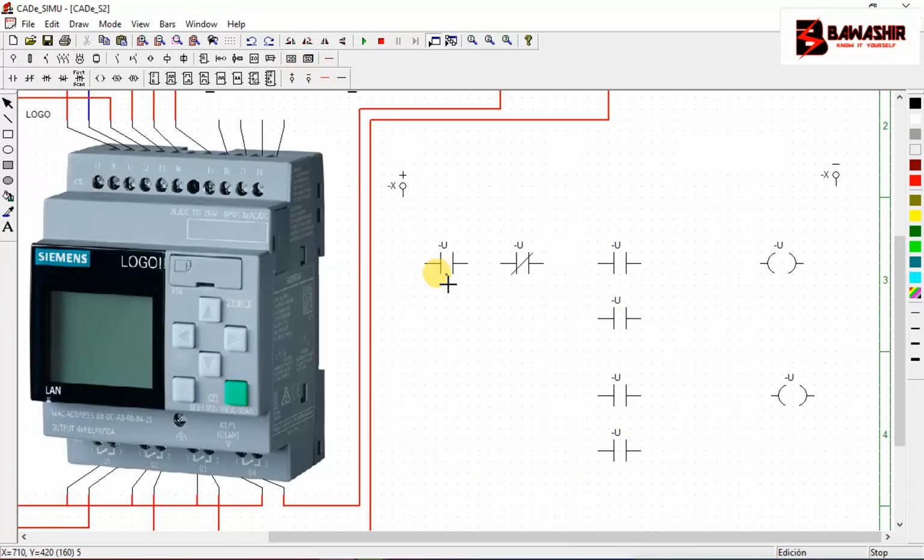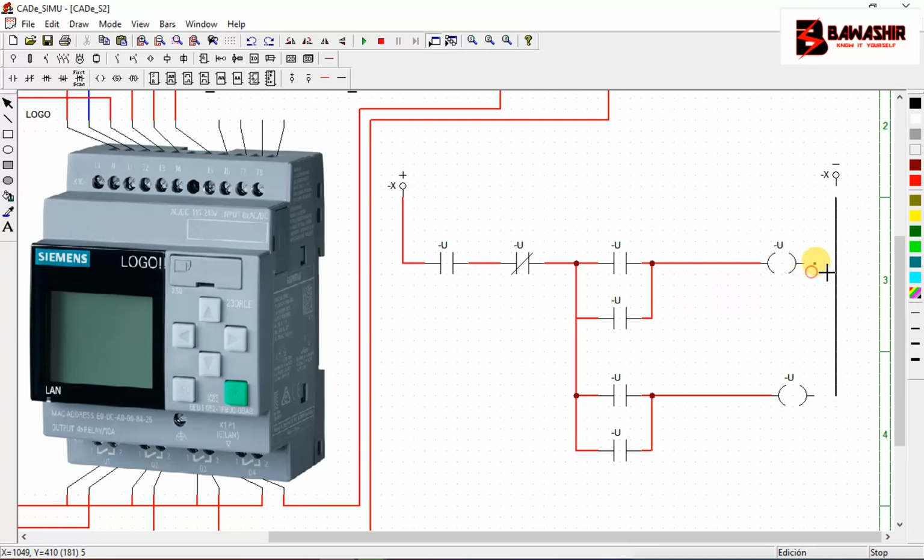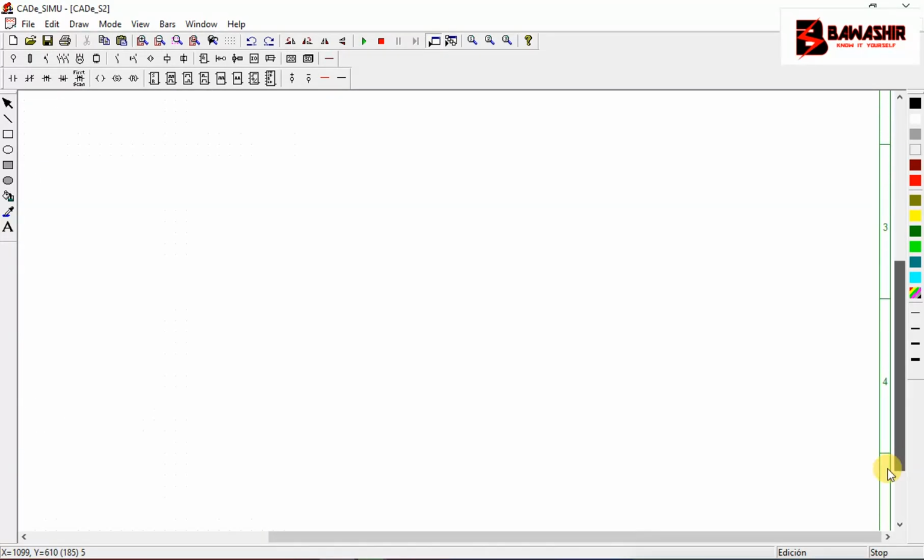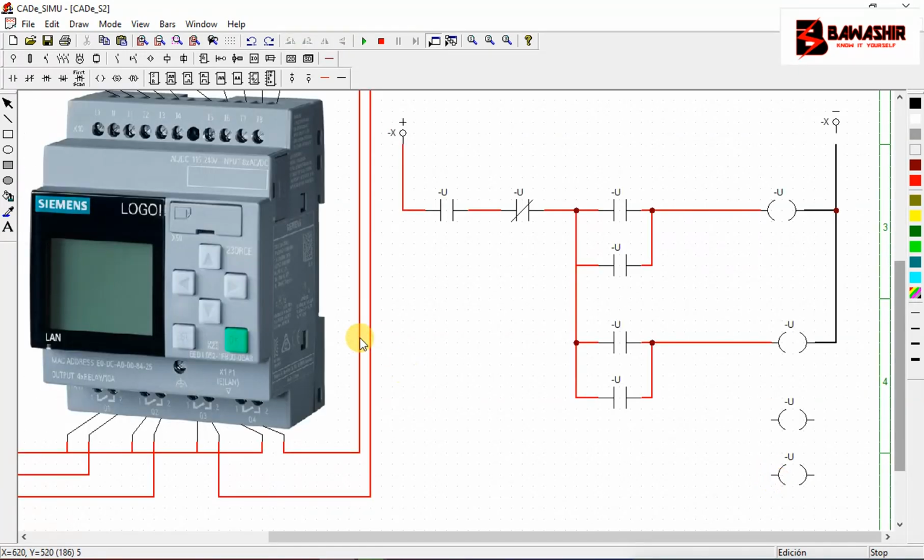There we go. Now we get our cable through the overload, through the stop, through the start for forward, then this one is going to latch up this way, like that. Then here to the coil, also here to the coil, and here is latching. Then here is also latching. Then we have our neutral, like that. Then we have our lamps, we shall have this one for the forward, this one for the reverse. We shall have them go through like this,